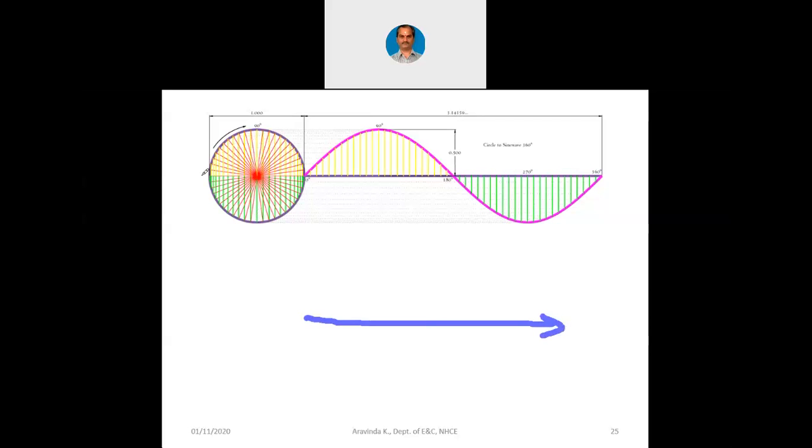What you may think is, when we make the wheel move and when we plot, we should get distinctly a half circle and a half circle. I am not writing it very neatly because I am using the mouse only to write. Now let me stop this. You will have to visualize this. You may think that we should exactly get a half circle at the top and a half circle at the bottom. But that is not happening. Why is it not happening? Because it is a minute movement which we are plotting. When we make a minute movement, the circle's movement itself is going to result in a sine wave.